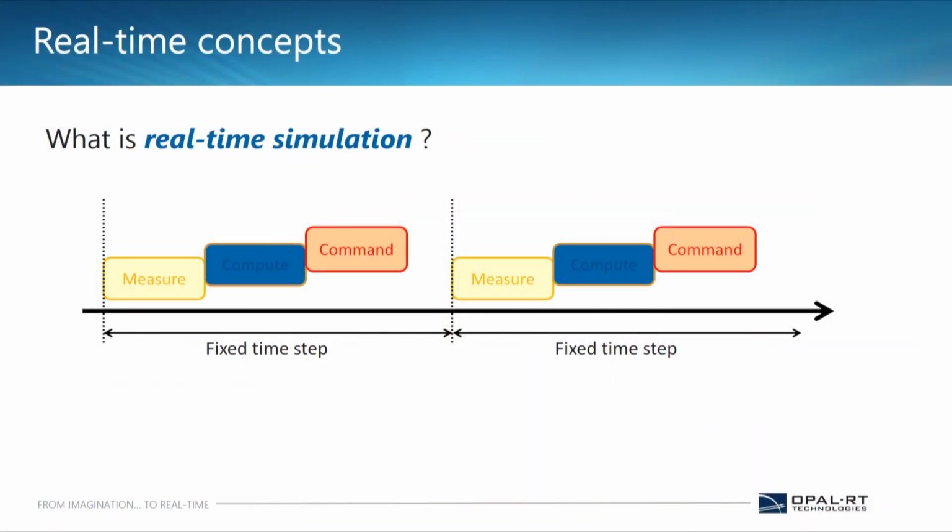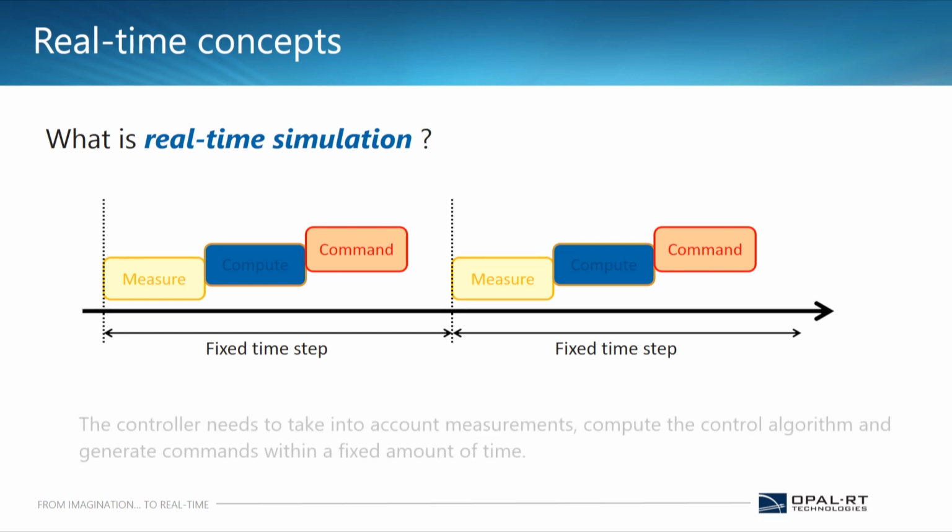to regenerate the results. The figure shown here shows that when we are performing a real-time simulation, within this fixed time step the entire model that has been designed will be computed, the results will be taken, and the commands will be generated. This process will happen for every time step. As I said, if you are running the model for 10 seconds and the time step is 10 microseconds, then for every 10 microseconds until 10 seconds is over, this process will be repeated.